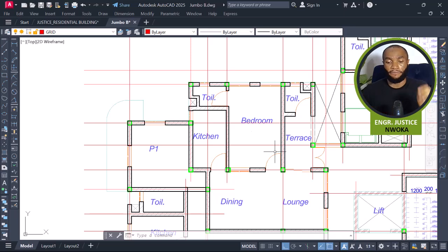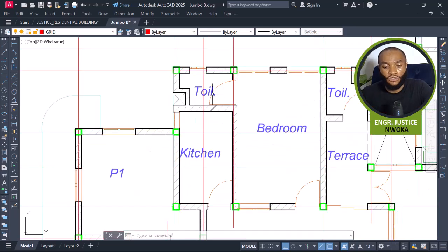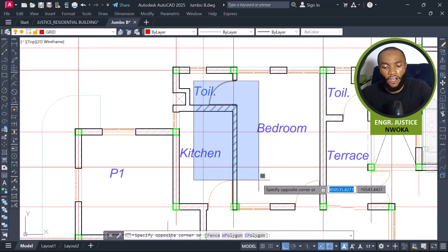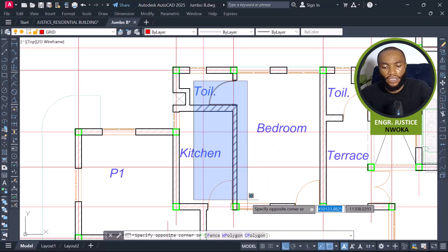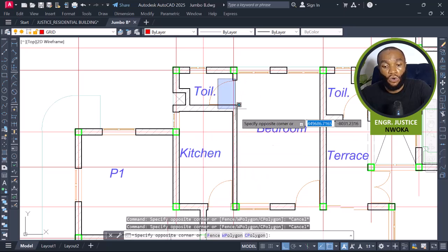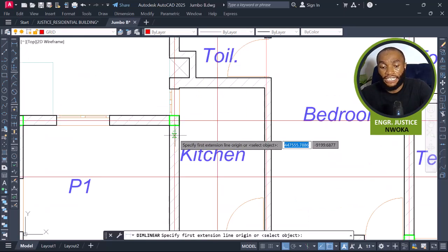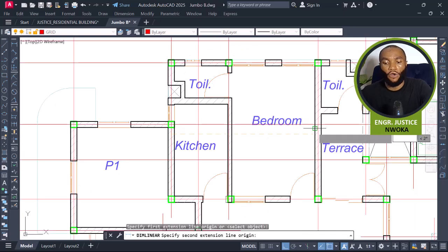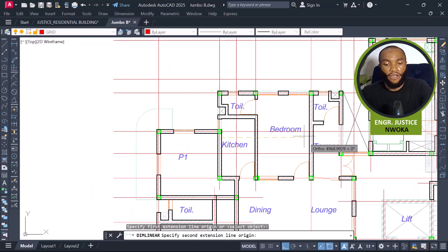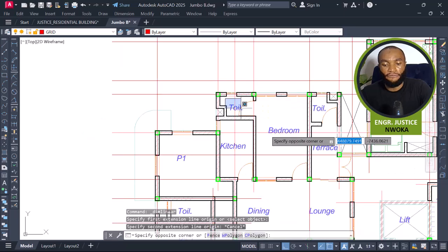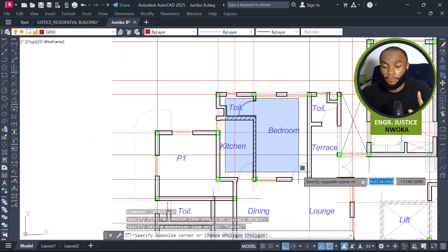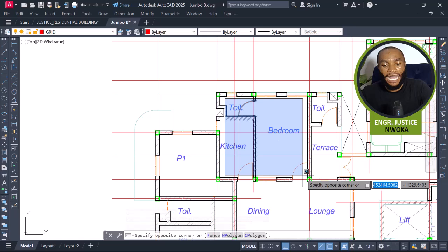Okay, that's fine. So with this now, I will have to eliminate this wall here. So I will not use this wall as a beam. Now, before you cancel any wall, make sure you have checked the square area of that panel. So if I want to use this place now as a full panel, to combine it as one panel, I must make sure that this area is less than 30 meter square area.